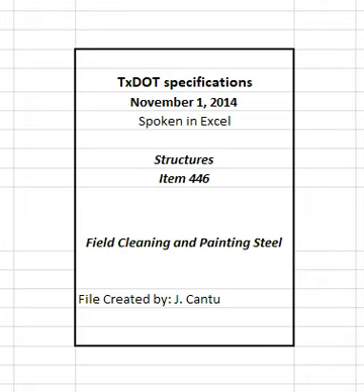3. Equipment. Ensure spray equipment has adequate capacity and sufficient gauges, filters, agitators, regulators, and moisture separators to ensure delivery of clean dry air at the proper pressure and volume. Is adequate for the type of paint being used. Has spray heads that provide a smooth, uniform coat of paint. Will remove moisture from airstream in contact with the paint, and has no dried coatings, solvents, or other foreign matter on surfaces that paint is likely to contact. Maintain all equipment and accessories in good working order.